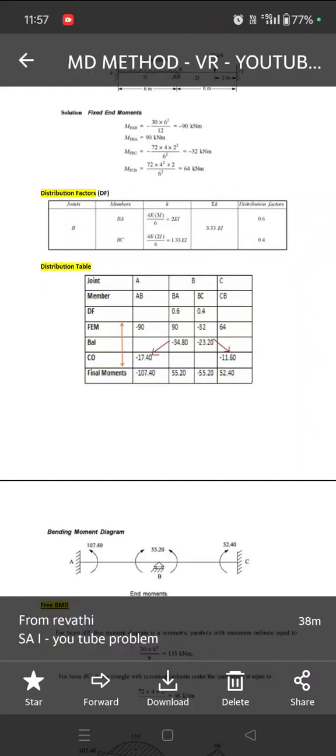Moment distribution method is applicable for analyzing indeterminate structures like continuous beams and rigid frames. Rigid frames with sway and without sway can be analyzed using this method. This method is based on an iteration procedure. Before the invention of computers, any number of members could be analyzed using this moment distribution method. It is the advantage of the moment distribution method.